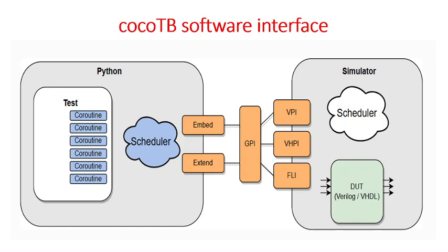What are these test cases capable of? They are capable of running a clock. They are capable of applying inputs and reset. They are capable of writing to the input port and reading from the output port of the design. This is entirely Python code we have to write, in which we utilize the cocotb libraries and objects for developing various test cases, because this is more hardware oriented. For example, we have to match the timing also. For example, we should generate a particular clock with this much on time and off time duty cycle.